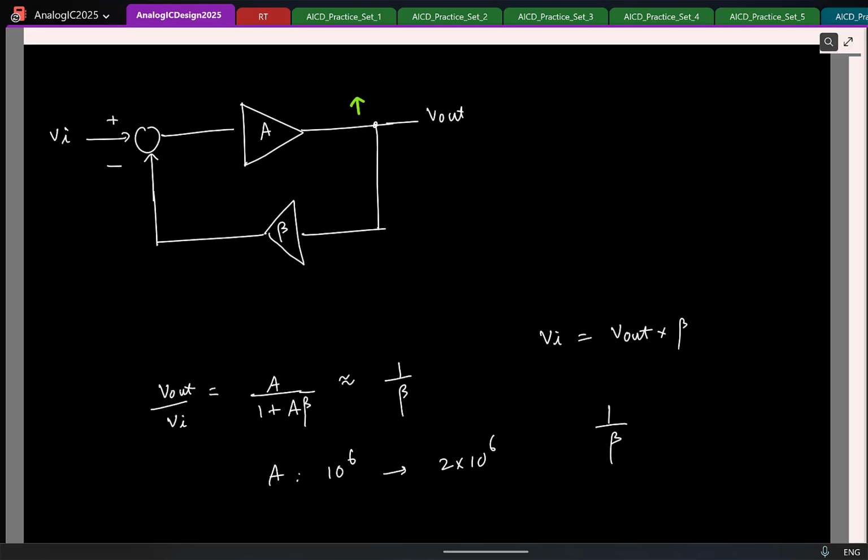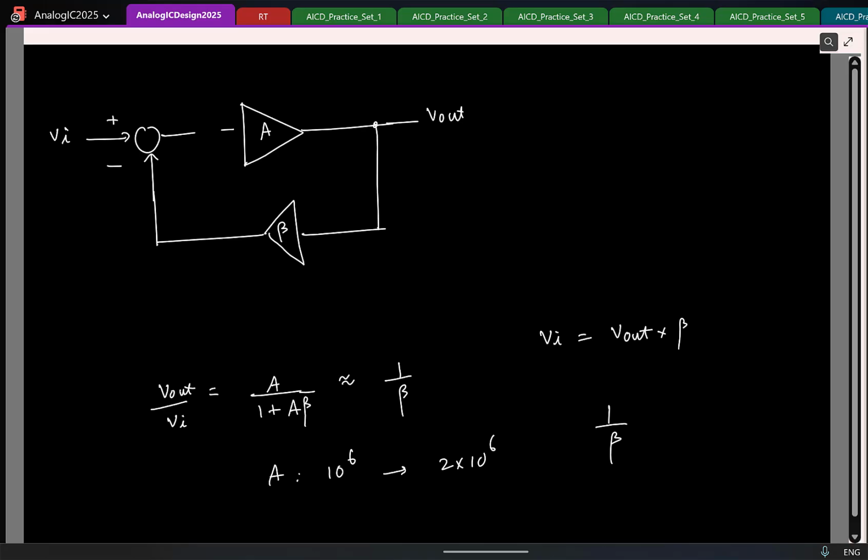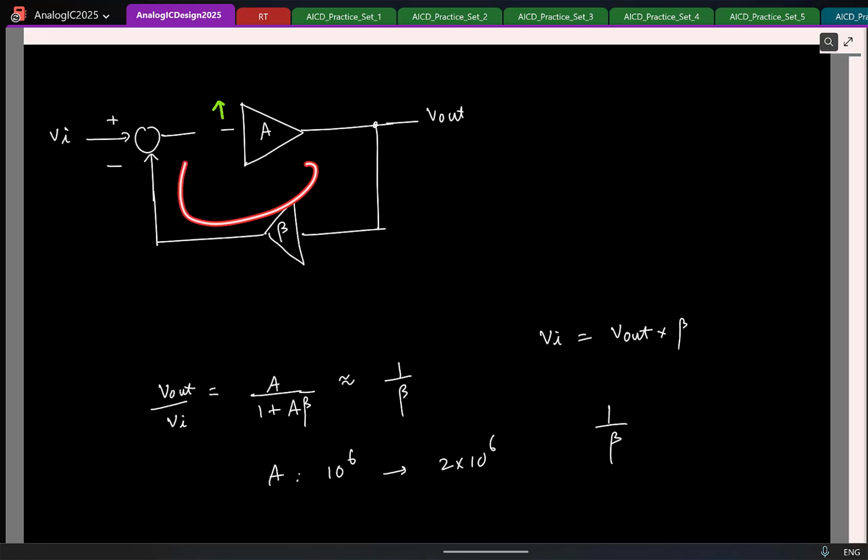Yeah, to check what kind of feedback loop our loop is, you basically break the loop somewhere. This is an ideal block diagram. You can break the loop anywhere. So let us say you break the loop here. Assume that some signal here is increasing or decreasing, doesn't matter. So you trace around the loop. If the loop is negative feedback, so what should happen here? Should the signal here increase or reduce? It should counter it. So let's check it.